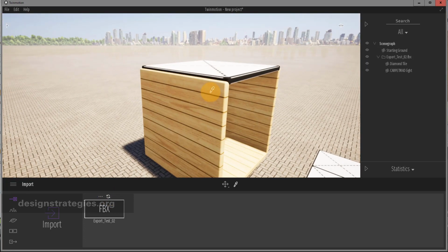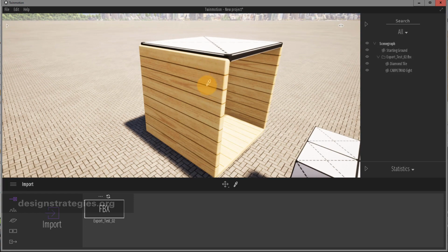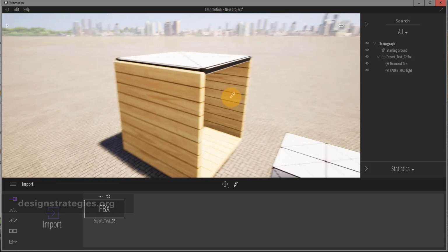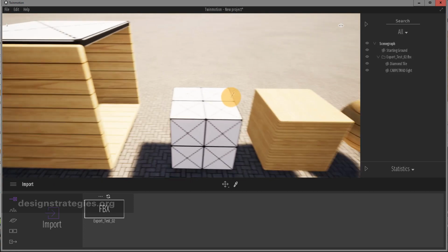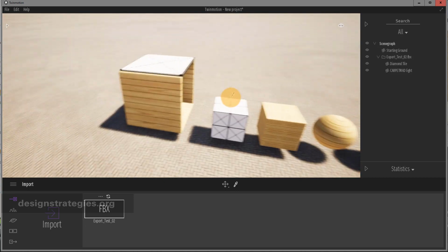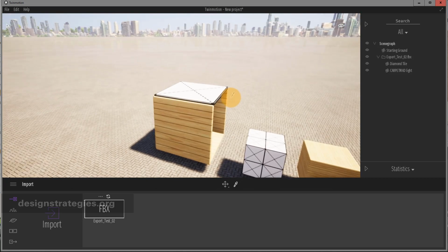And here you can see that my mapping works really well if you use the right mapping channel and the bounding box probably in Rhino. I can even see the top surface just because I exploded my object before I exported this. The only thing which doesn't work is the decal, but I can live with this, especially when I know that in Twinmotion putting decals on my objects is a really easy thing.